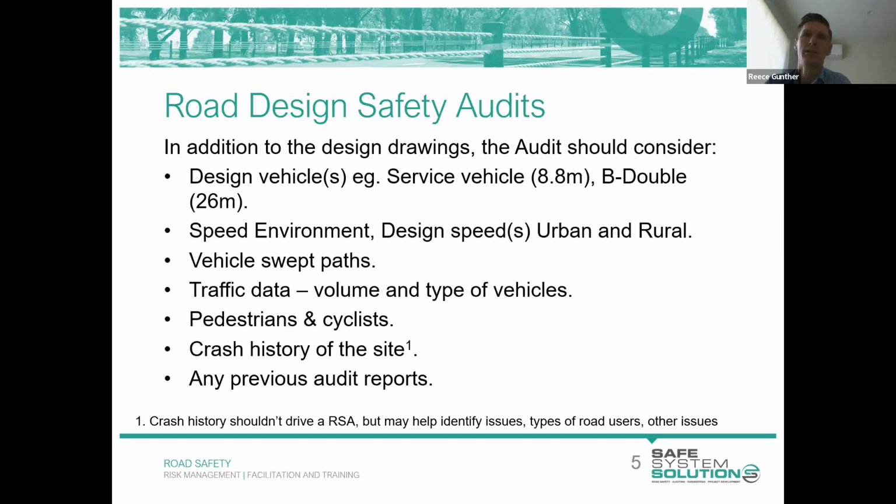In design road safety audits, there's some information we'd like to gather prior to starting the audit. Now, some of this information is freely accessible on the web, which is great. Traffic volume information, some of that is freely available. If we can get counts from our client, that would be great. But if we could obtain this from our client, if they have intimate knowledge of the project, that would be great because it provides us with a background of information to understand the design context.